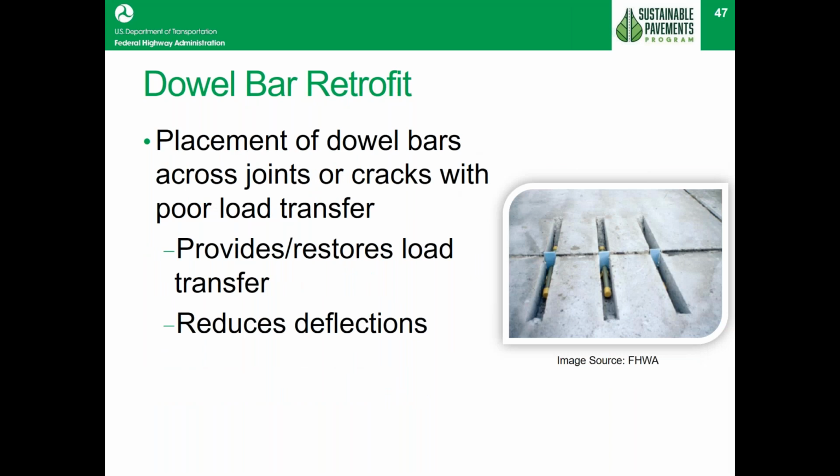Now, dowel bar retrofits. You may have seen some of these out there. You tend to see these marks in the wheel path of the roadway. We had a lot of these repairs that were done a number of years ago because there were quite a few slabs early on that did not have dowel bars installed at the time.